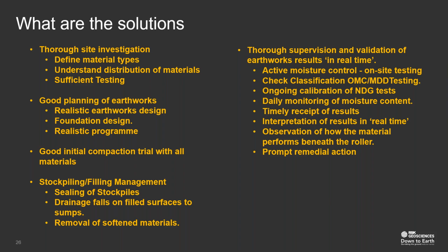And that may mean doing additional testing at the beginning of the site works, and then also further testing during the earthworks. We need to plan the earthworks appropriately, and we need a realistic earthworks design, which takes into account the limitations of the materials and the use that you're proposing, and it needs to fit in with the foundation solution.